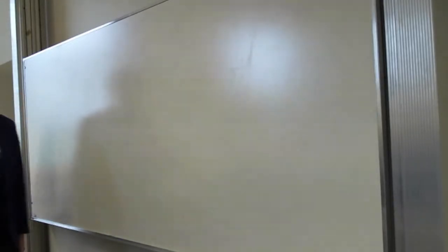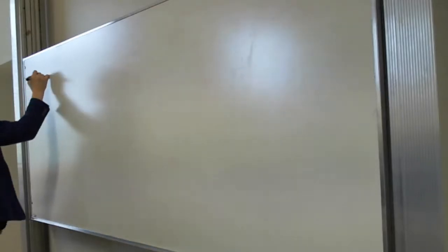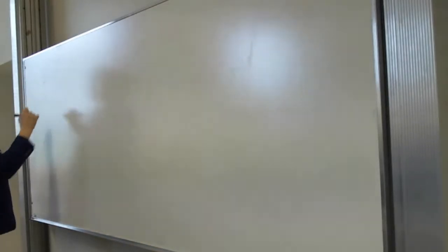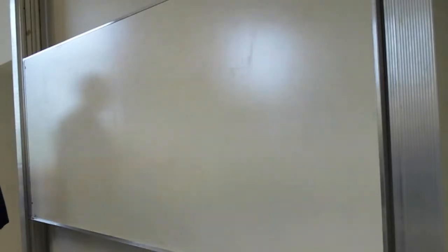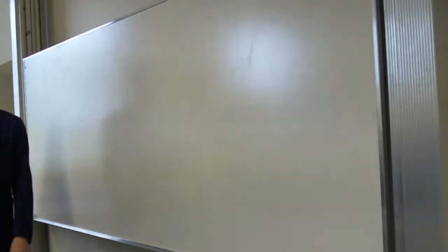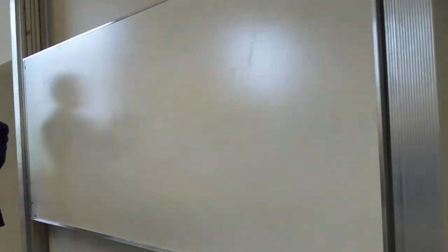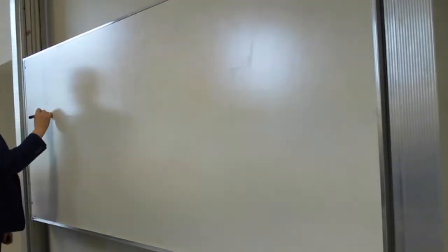The easiest sensor actually is just a potentiometer, because I noticed we also have some temperature sensors, LM35s. That's the most burnt device in the world. You just accidentally switch the polarity and it will burn. Smoke comes out of it and it doesn't work anymore.